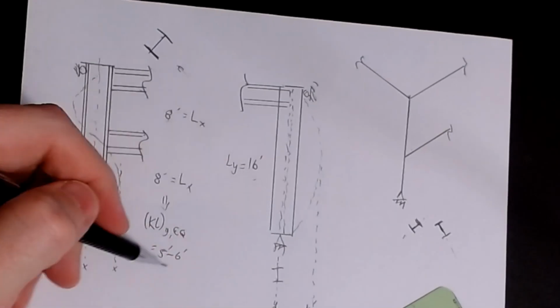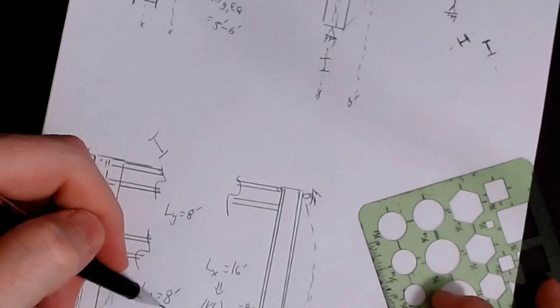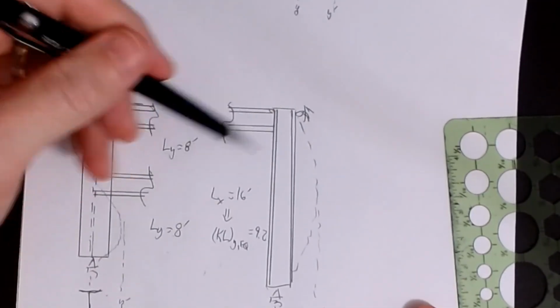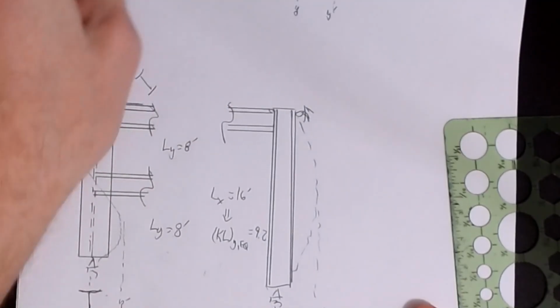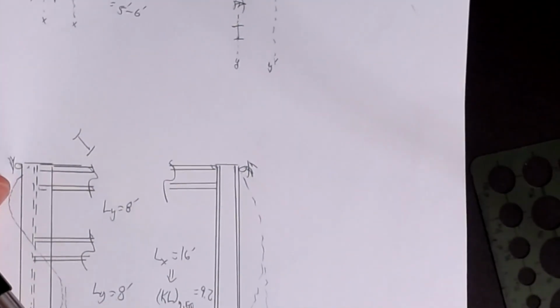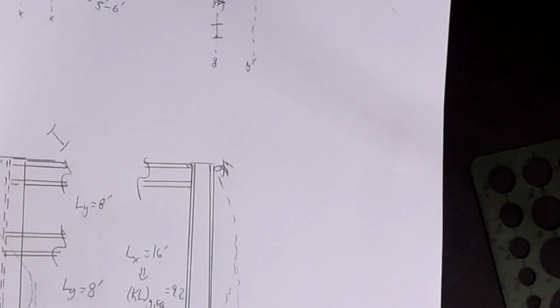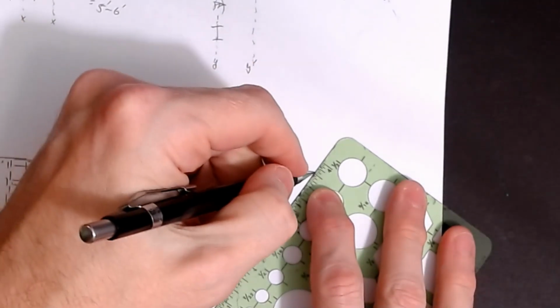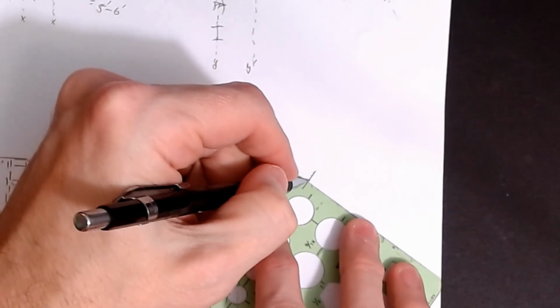Okay, 16 versus 5, or 8 versus 9.2. Which one's more balanced? Clearly this one. And so this would be the optimal orientation for why I would turn a column and decide to mount it so that for this particular scenario, I would orient it this way.